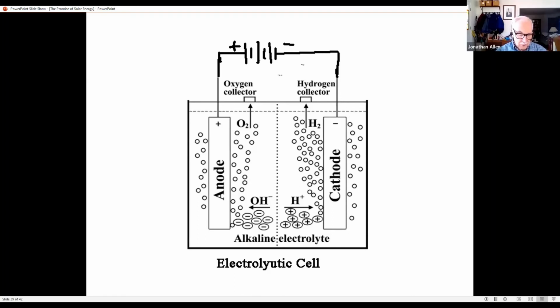Flywheels offer a means of short-term energy storage, only seconds or minutes. They're shown in the chart there, and they're especially helpful in replacing the inertia associated with the flywheel effect of steam turbine generators when they spin, and they can thus stabilize the grid against sudden changes in supply, or if a heavy demand is suddenly switched in.